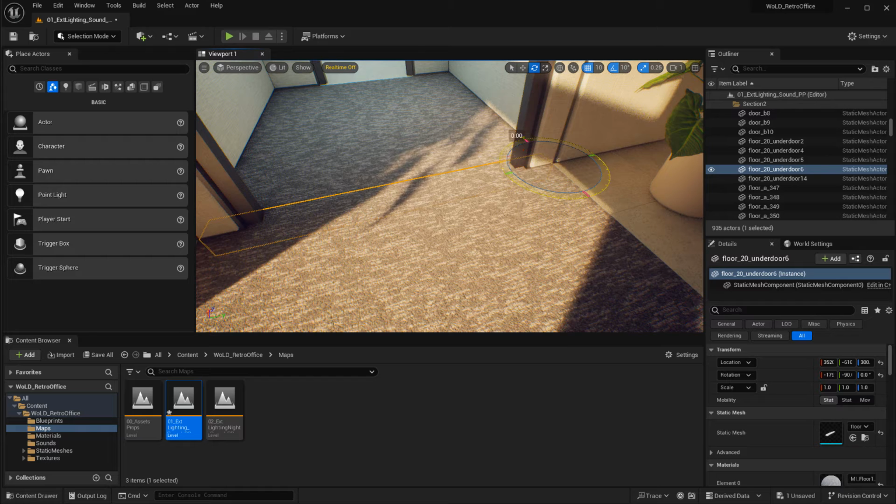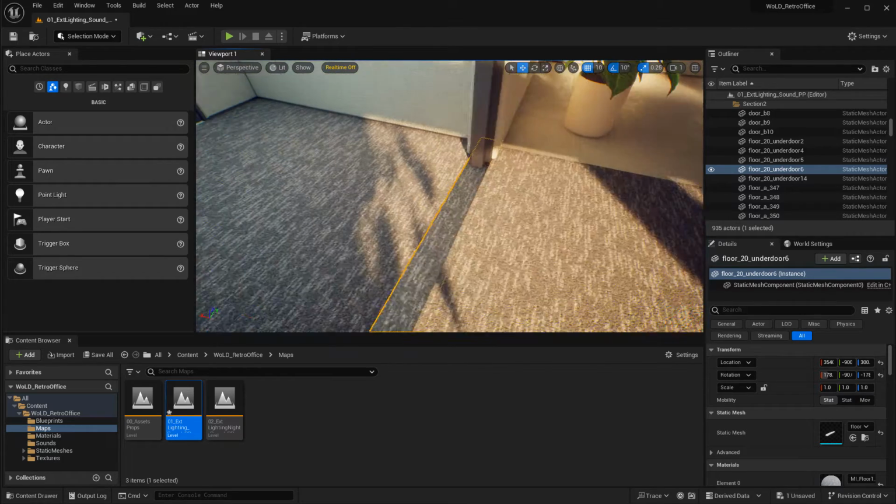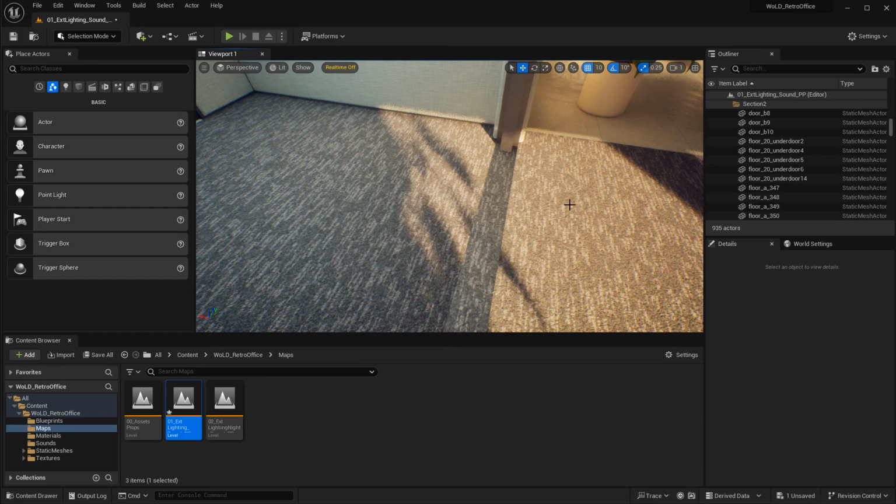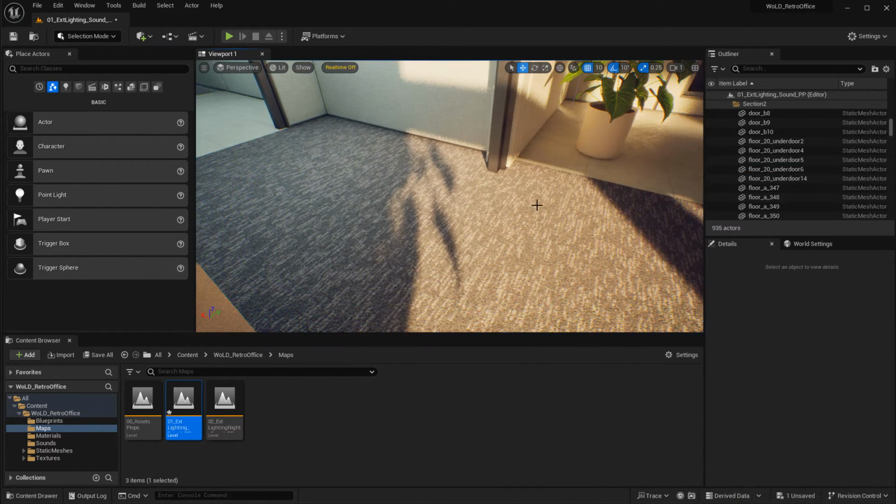And sometimes you may need to flip it 180 degrees to get the other side, then just align it and make sure you position it well. Keep working it until the seamless texture is aligned. And in this case, this one worked. So that's a workaround on certain pieces of geometry if you happen to encounter that issue.